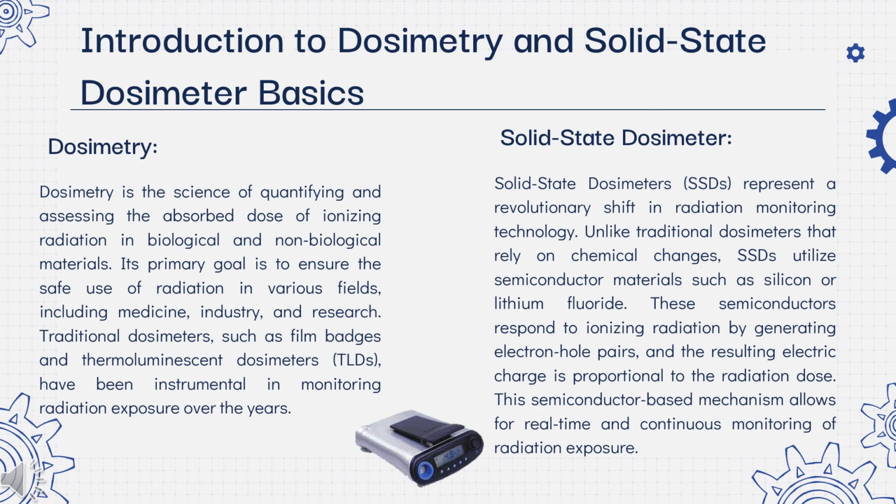This ionizing radiation generates electron-hole pairs, resulting in an electrical charge. We have a relationship between the radiation dose and the electrical charge. This relationship is proportional to the radiation dose. This semiconductor-based mechanism allows real-time and continuous monitoring of radiation exposure.